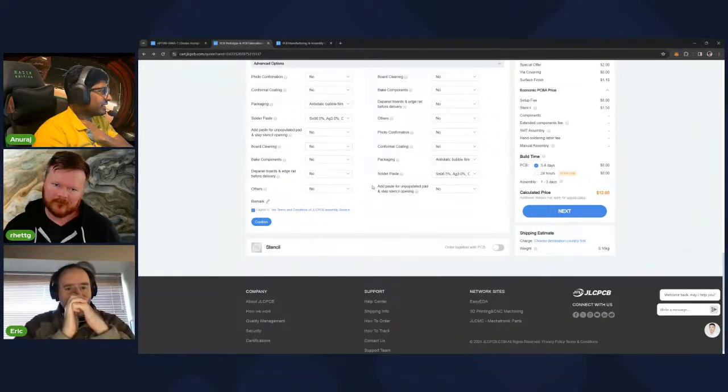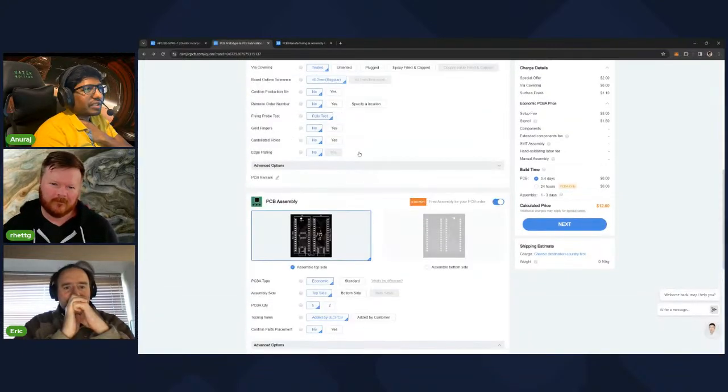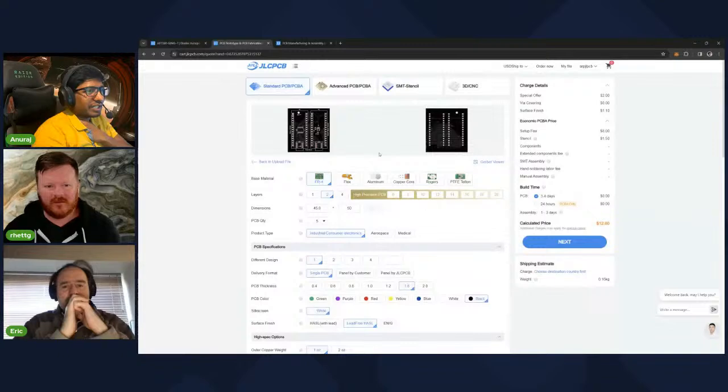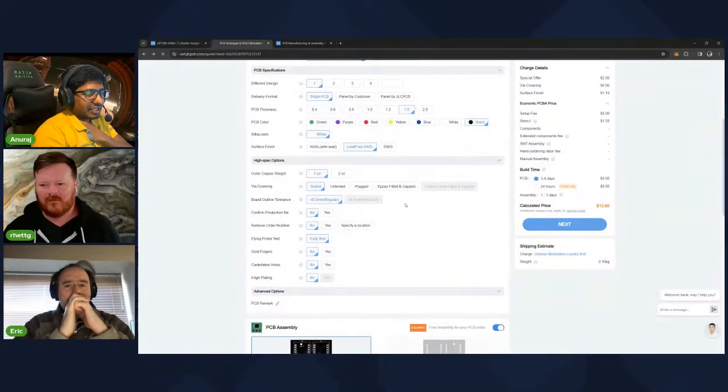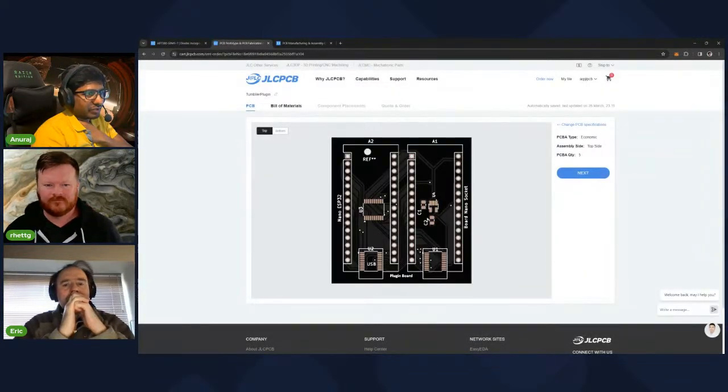The Gerber file might not have the related position, or maybe it's in one of the files, I think the CPL. Yeah, I think it was in the Excel file that the position was not correct, and that's why one of the components was not correctly placed, and I had to correct it here.